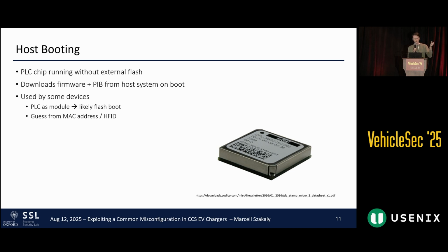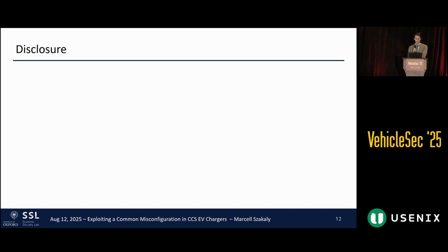If the PLC chip is an integral part of the circuit board design, it's more likely to be host booted. Host-booted systems, because they don't have any persistent storage, are somewhat immune from this attack because you cannot put a configuration on there forever. However, until the next reboot, it is still vulnerable.